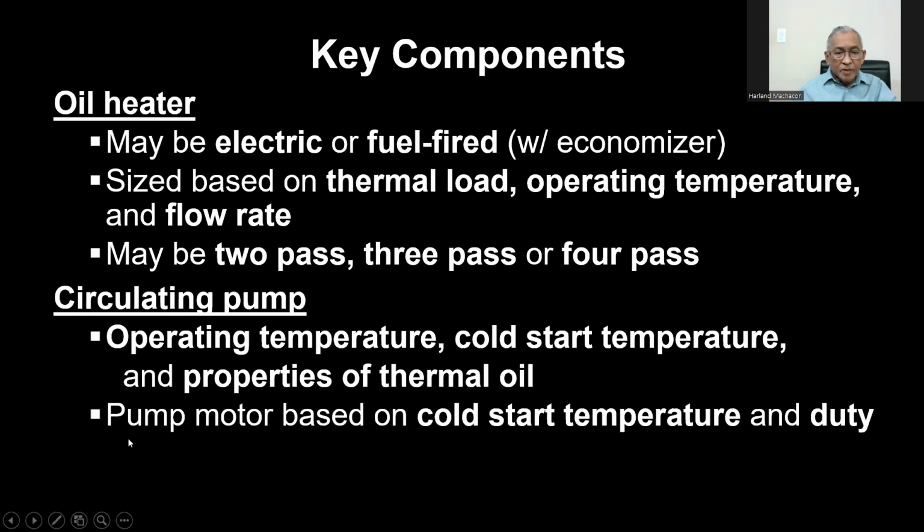The circulating pump is sized based on the operating temperature, the cold start temperature, and the properties of thermal oil. The pump motor is based on the cold start temperature and duty.